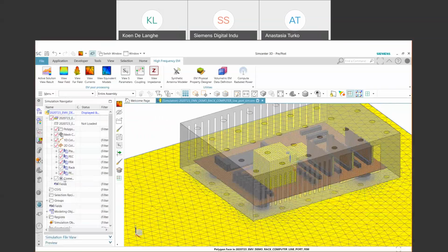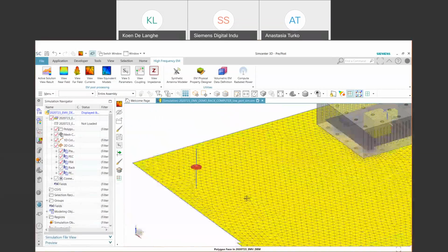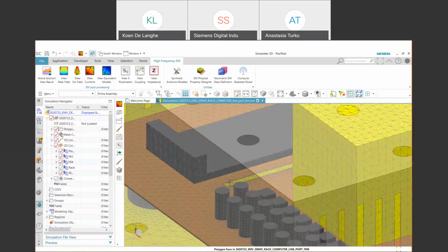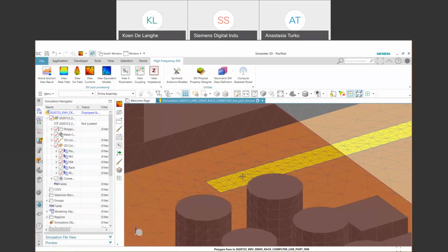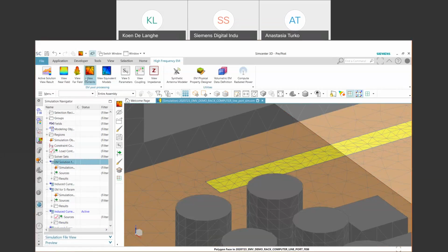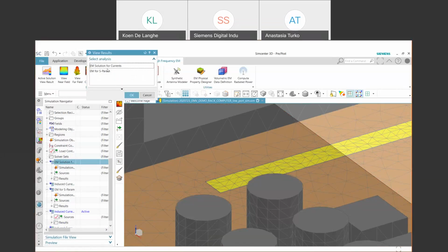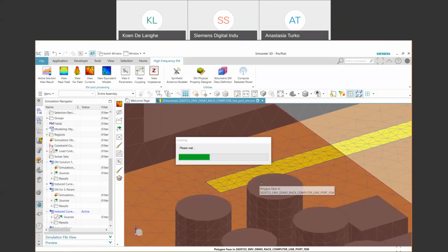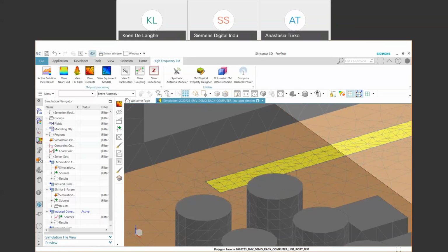And with that mesh, we can then do the analysis, meaning we put an excitation, an external interference source, there, and we calculate the port results in this line. What is going to happen in this sensitive part over there? So we created the EM solution with the sources here. And from that, we can calculate and visualize S parameters. For example, I can show S parameters for the different ports. I'm going to, sorry, it's always happening on another screen.